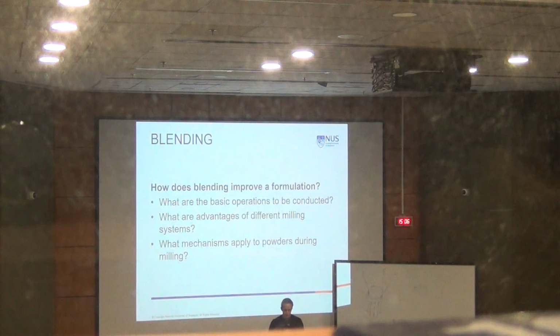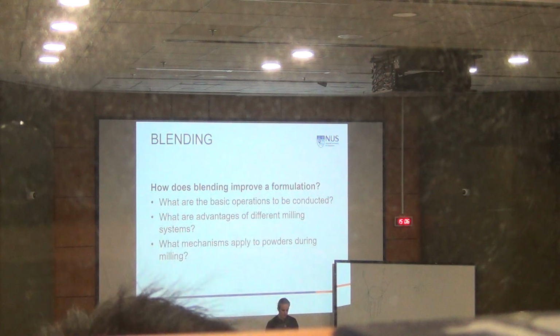This is also what I want you to understand about blending, mostly what the basic operations are. You should understand it's a dispersed system. When I do the blending, the principle is to give mechanical energy into a system to create this dispersion, and by that I also overcome all the other effects, like for example gravitational force. By putting energy into that, I more or less have to work against the usual forces that are affecting the powder.